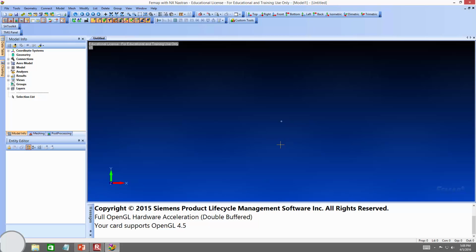So now that we went through that quiz and everything, let's actually get to doing some modeling. All right, so we got FEMAP open. The first thing that we're going to do, and this is sort of the same thing we did last time, is create the geometry. Now, the geometry for this problem is fundamentally different than what we did last time. Last time we created a 3-dimensional object inside FEMAP, an object that had length, width, and height. We're not going to do that here. Here, we're literally just going to draw a bunch of lines, and that's it. No extrusion, none of that, okay?